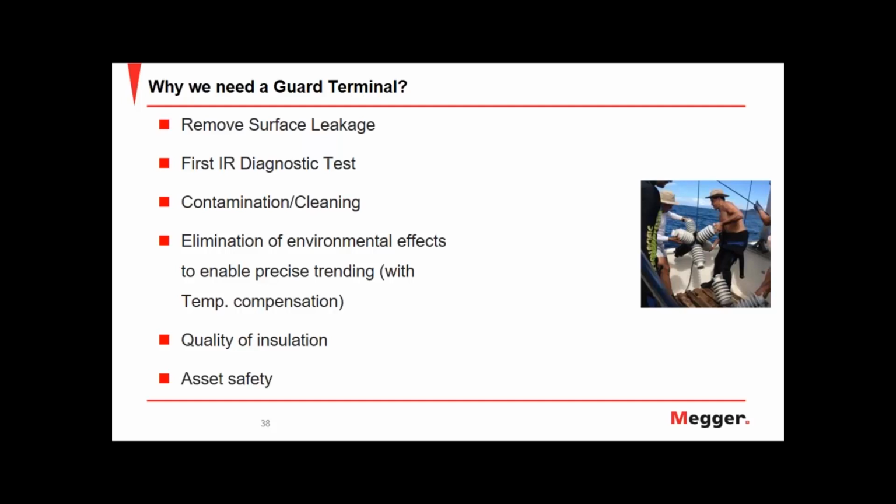By using this very first diagnostic test, we can readily determine if the asset's insulation is really producing a low IR value, that it's actually degraded, or if it's just contaminated. If it's just contaminated, we can simply schedule a cleaning operation and restore the asset's IR value to safer levels.